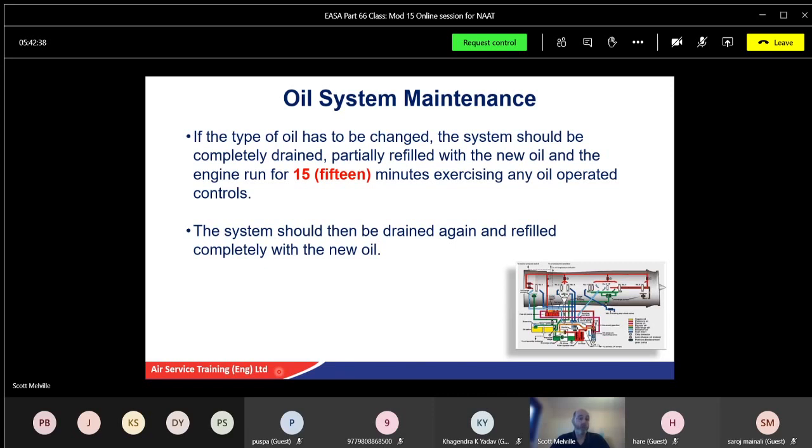So although it was a recirculatory oil system, by the nature of the type of system, it would actually go through quite a lot of oil. So it wasn't a total loss system, it was classed as a partial loss. So we didn't have to change oil, we just kept topping up, so it was cleaning itself as it was going through, but certainly some of the commercial engines, they tend to keep it in. You will have to top up every so often because you will lose small droplets of oil through the breather and that sort of thing as well.